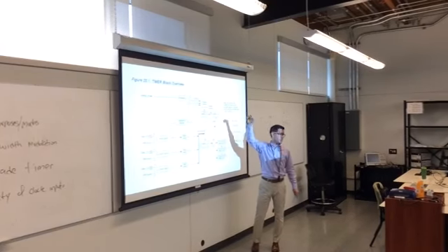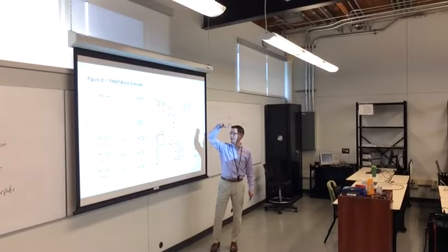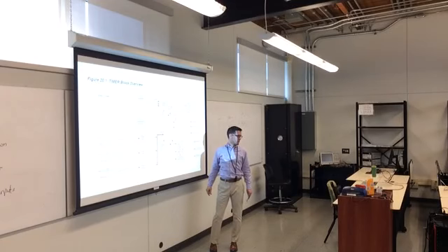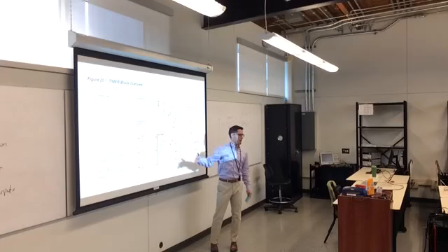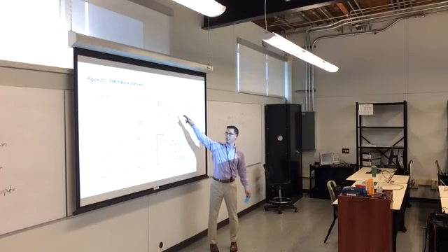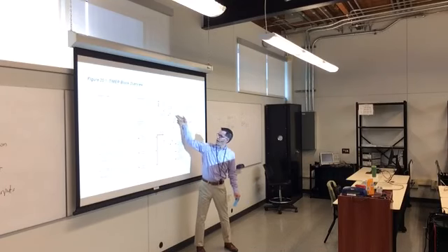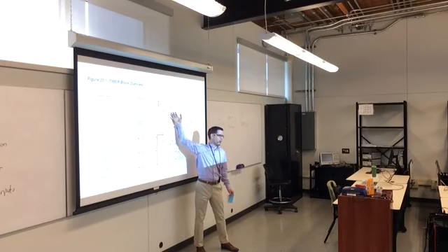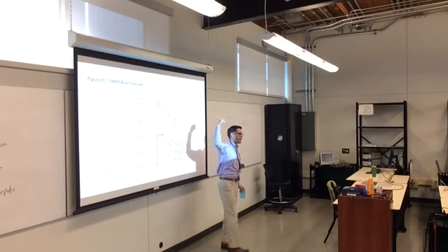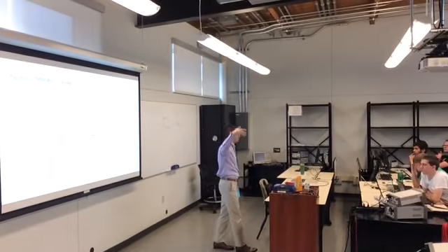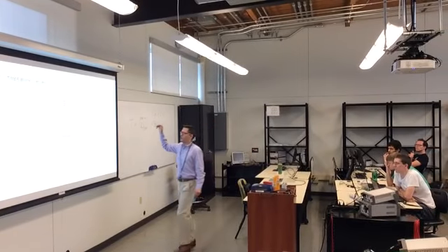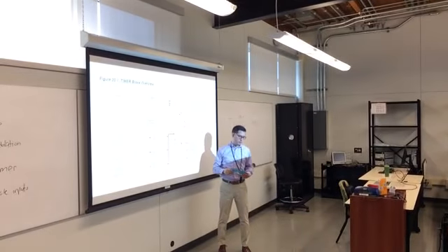Give me another one you think is important. You have a pick of lots of boxes. Pick a box. Yeah, timer top. So remember, the timer's current counting value is always going to get compared to some top. If you don't have the top set, it just rolls over when it rolls over. So this is an important one as well.